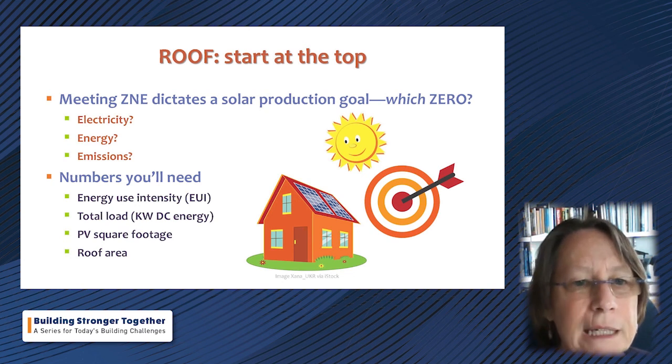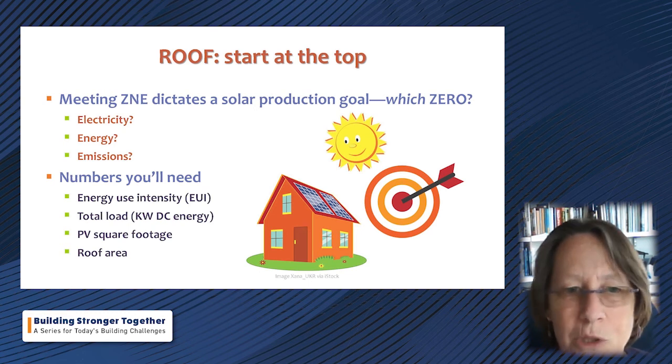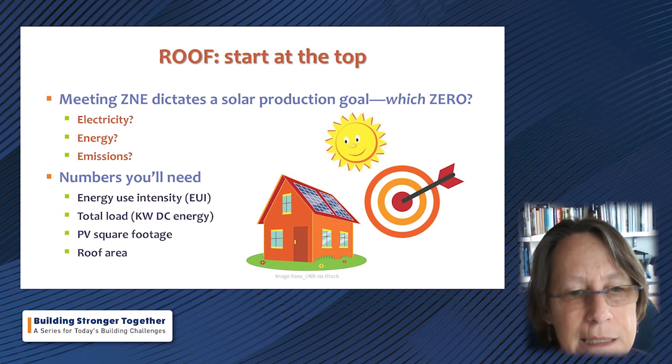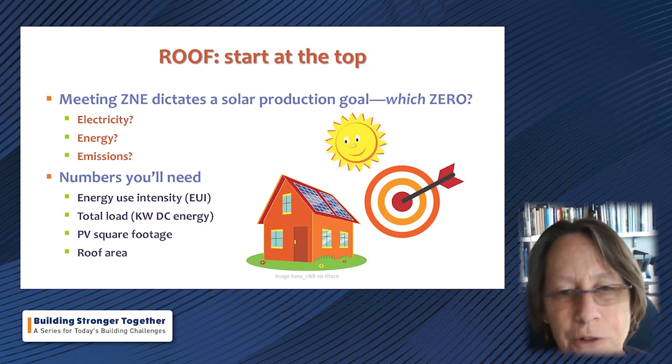First of all, getting a target EUI, energy use intensity, which is measured in thousands of British thermal units per square foot per year, is a simple lookup process. So we have those numbers here for California from a research study that's linked at the bottom of the page, and I'm giving an example here, Climate Zone 3 in California.